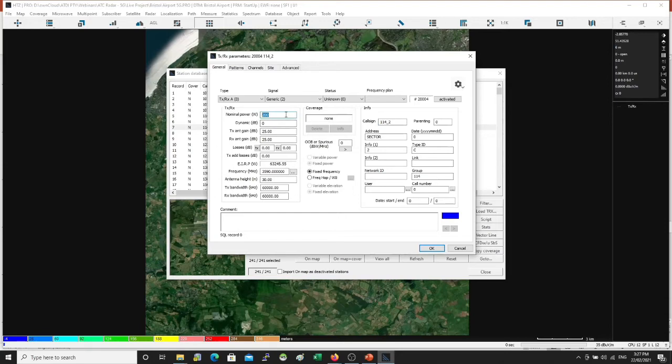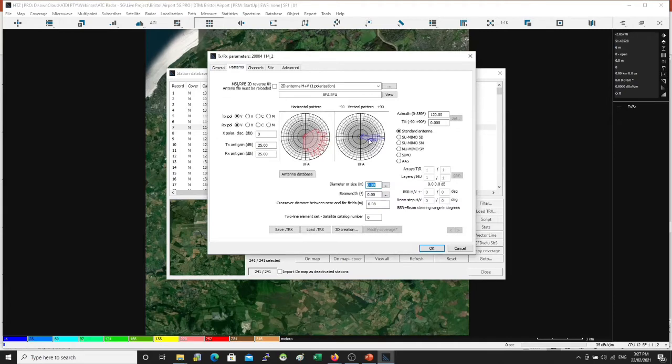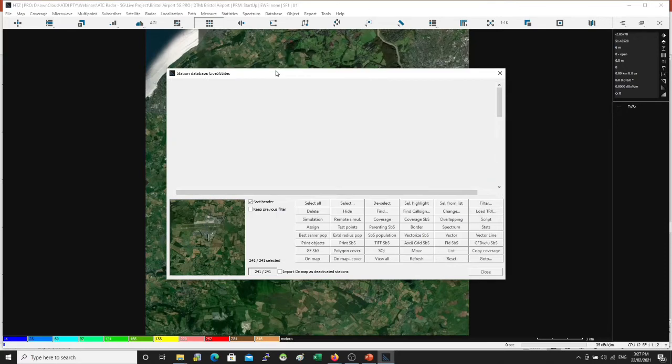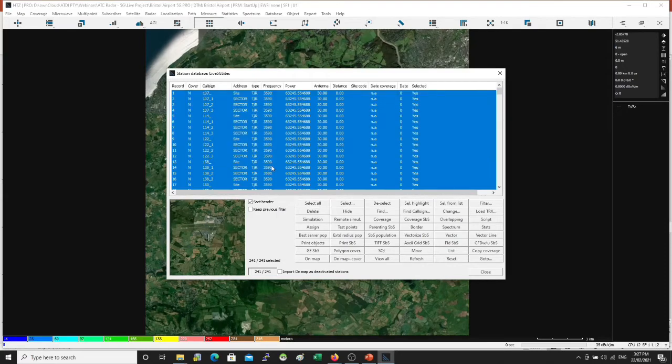Now sometimes you don't have to model it as 200 watt. You need to look at your setup. Sometimes you need to do it 100 watt or 20 watt or 40 watt, depending how much overlap you have with the in-band. So we have the antenna gain coming correctly, we have transmission frequency coming correctly, antenna height coming correctly, we have antenna pattern, actual orientation coming correctly. So all the important information are in, okay? So the importation process was successful.